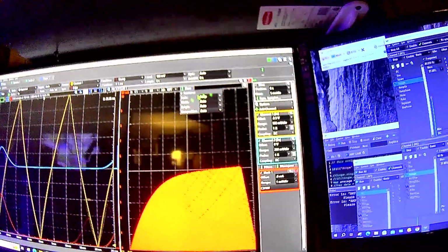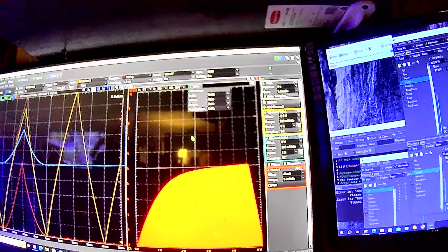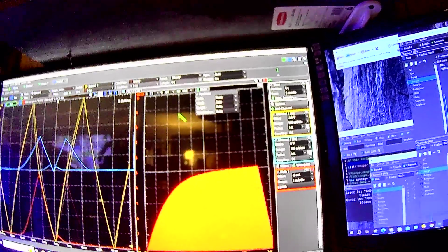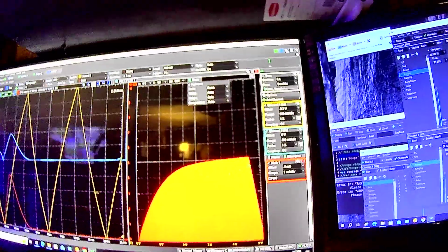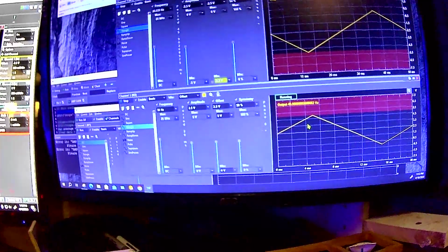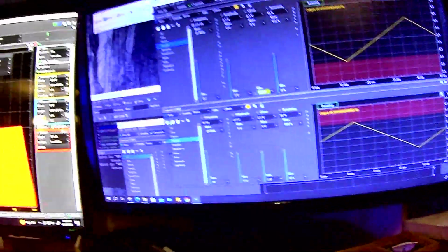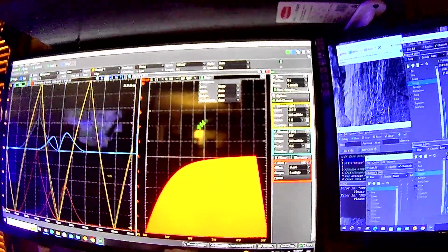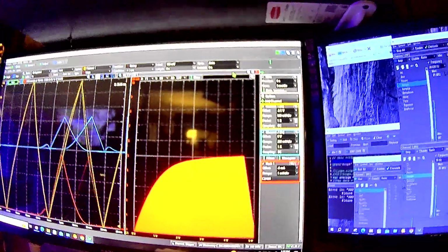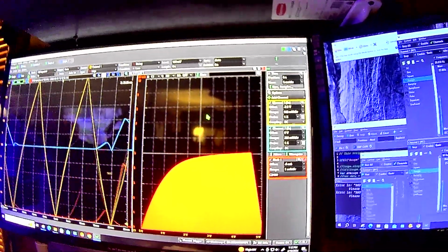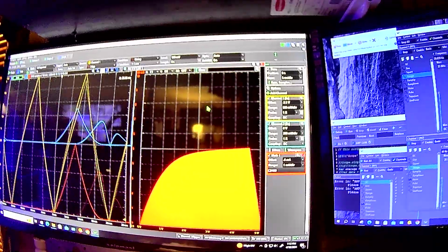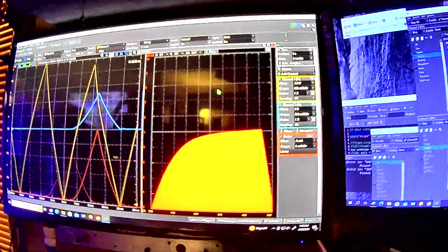And show you what it looked like in the positive region, because as long as you control the current, you can do that, but you're not really getting amplification, because you forward bias the diode typically when you do that. And at this point, it's not doing it all the time, because I am still sweeping the drain source voltage, right? So it wouldn't be forward biased all the time, but you saw that it was operating significantly in the forward bias region. But basically that means at some point you're forward biasing the diode, so that's causing the device to act funny.